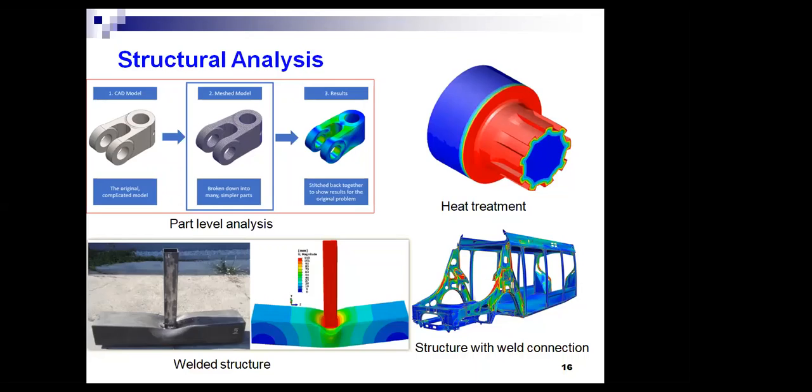We have to consider the manufacturing methods through which it is manufactured, because we do not know the influence of the manufacturing process on the system. So in general, we neglect this at the concept level design, the concept stage. But manufacturing processes like welding, casting, forging, in which the material nonlinearity is highly influencing the strength of the material, will influence the design.